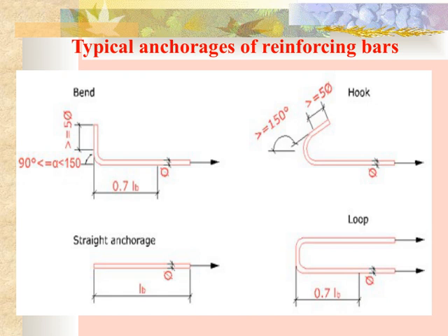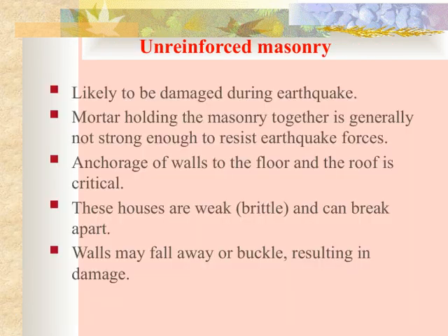This is especially vital in tension zones, where the bars are primarily resisting pulling forces. Proper anchorage prevents slippage and ensures the load is transferred efficiently from the concrete to the reinforcement. Connecting this to our overall theme, understanding these anchorage details helps us design safer, more reliable structures that perform well under load. It's a fundamental aspect that influences the integrity and longevity of our concrete constructions.